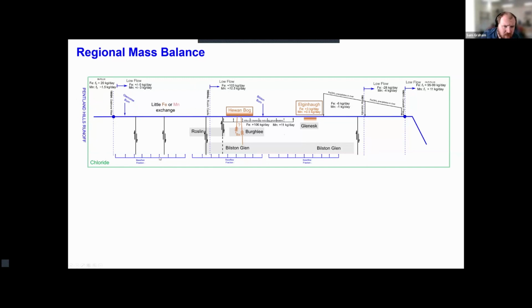Even though there are some faults through some of the stratigraphy and a few shallow workings that aren't necessarily named, there's surprisingly not much of a net addition to the system. But once we get into the coalfield proper, which is where our geobattery is sited, we suddenly find that there's a net contribution of 103 kilograms a day of total iron across a fairly large section of the coalfield. The question is, on a more granular basis, where does that contribution come from?